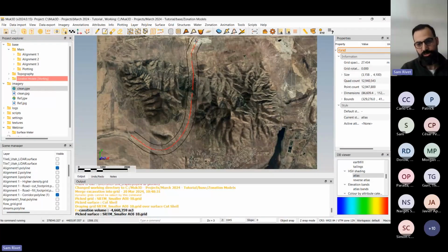You're going to send that information to your surveyors. We're going to stake that. Operations is going to go out there and strip exactly within that footprint to minimize the amount of topsoil you're producing. But once again, you don't know where your road's going to be in advance. So just strip everything, design your road, establish where your road's going to be, and then you can restart and then just strip in those areas.